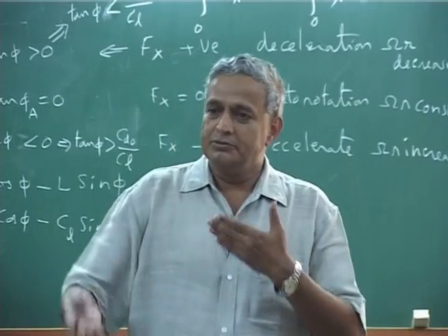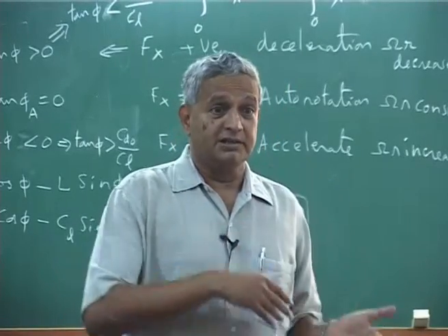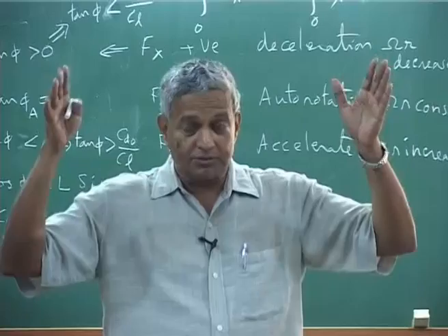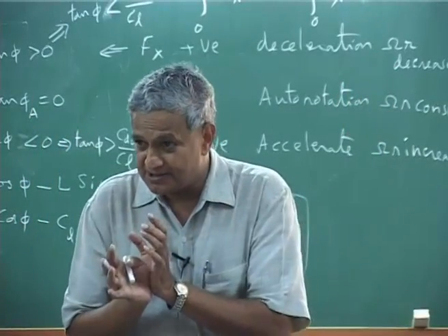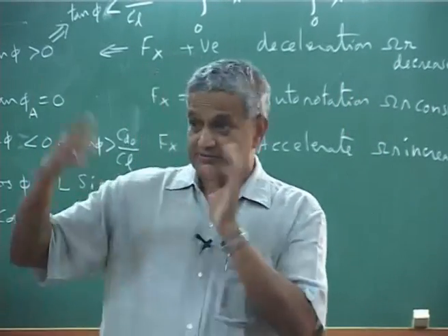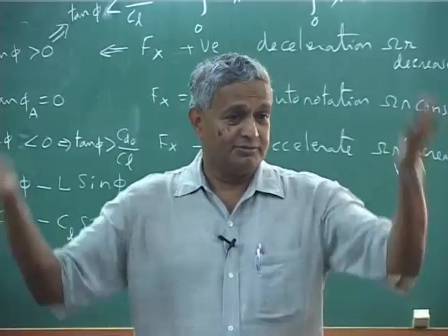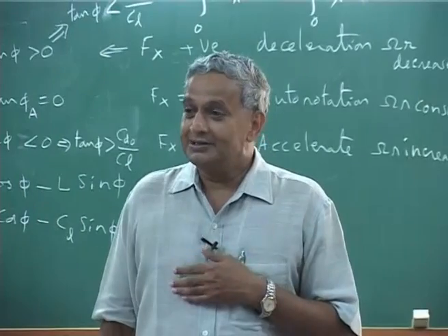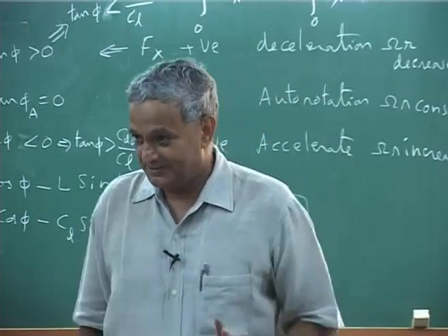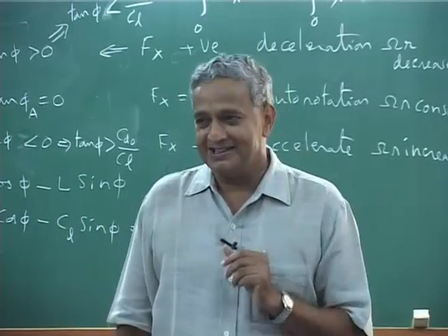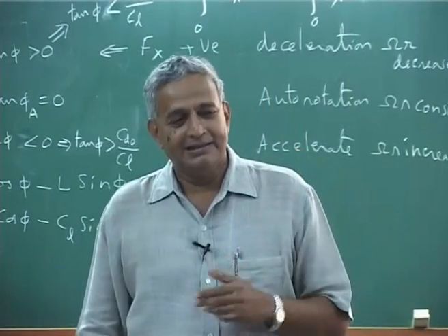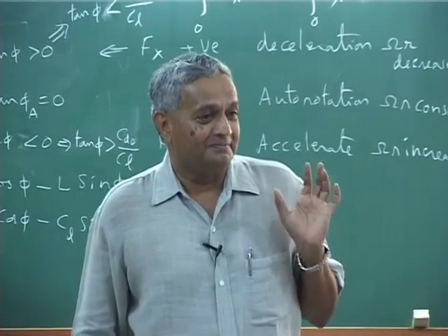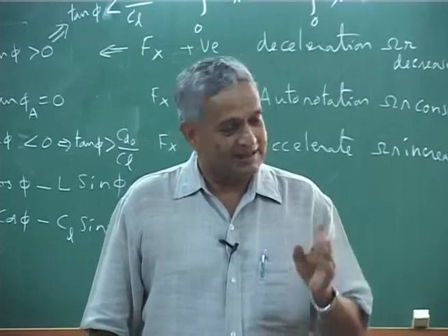So, how do you take the inertia? What inertia should you take, so that the rotor has sufficient inertia? Because if it is very large, then the aircraft is going to be very heavy, the blade is going to be very heavy, but if it is very light, the blade will stop. So, you should have sufficient inertia, and there are some guidelines, at least that much inertia of the rotor you should have. So, that is another aspect.